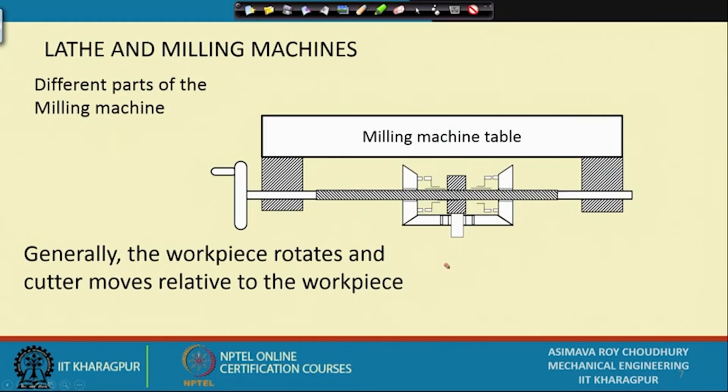It's something like this. Looking from the top, we have this to be the table, this to be the screw, these to be the bevel gears, and they are rotating on top of another bevel gear, and inside there is the nut, and on this side there is the clutch.